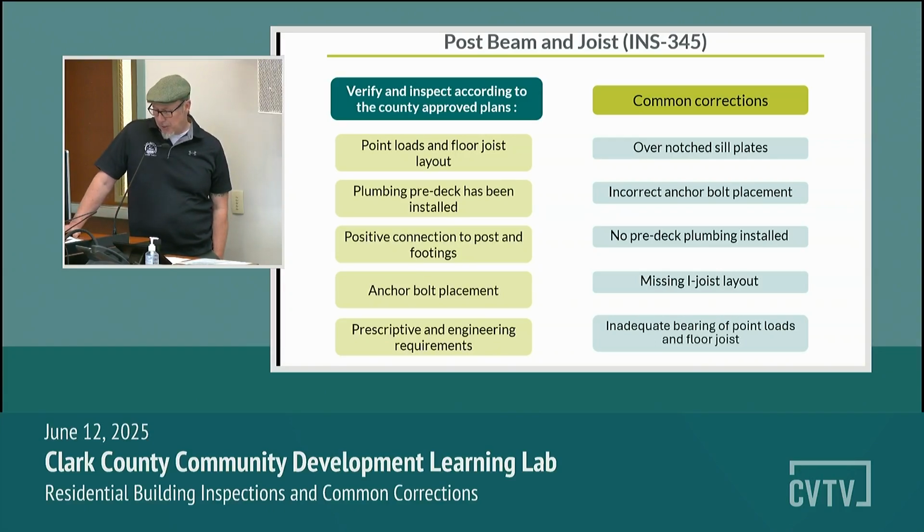And a sill plate is a horizontal piece of wood that sits on top of the house's foundation. It acts as a bridge between the foundation and the rest of the structure. It is a critical element that helps distribute the weight and secure the building to the foundation. So if that plate has been notched more than 50%, then we'll need another anchor bolt within 12 inches.